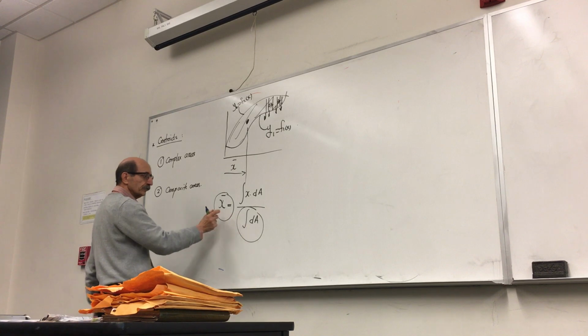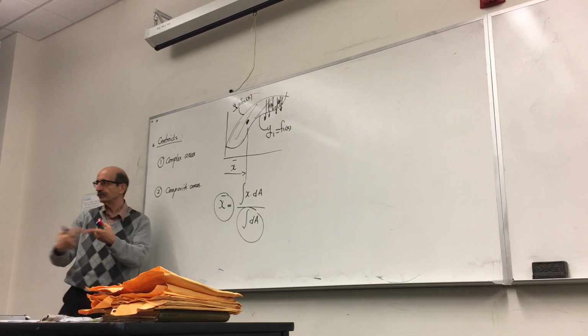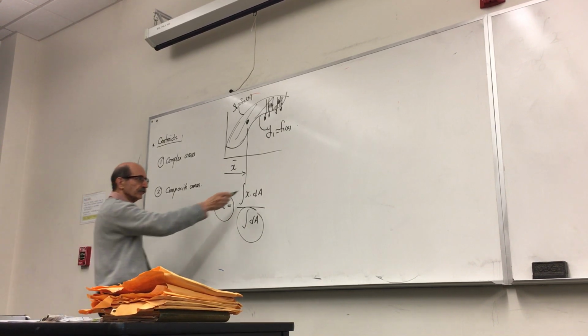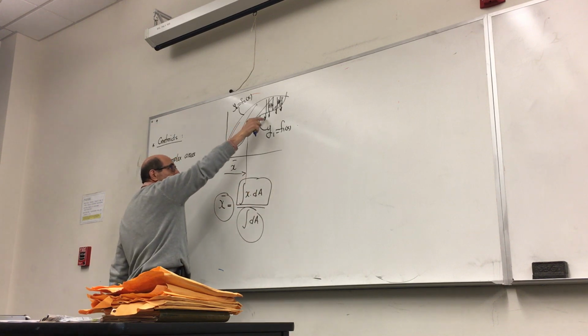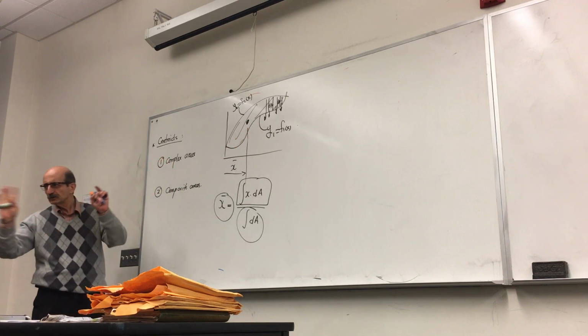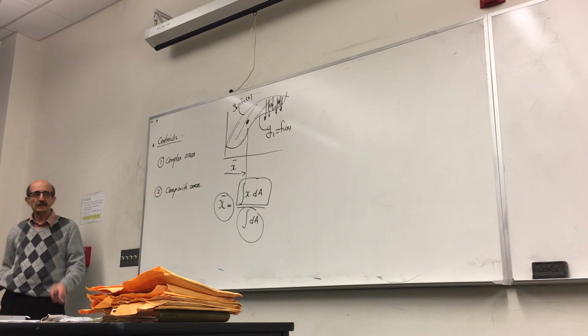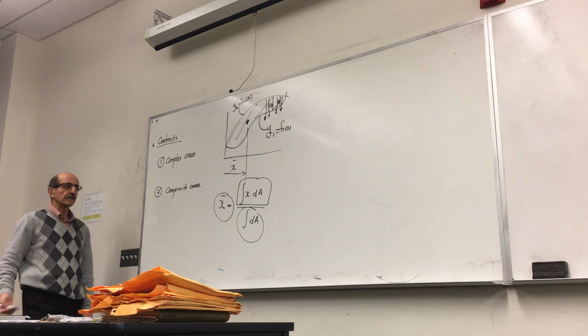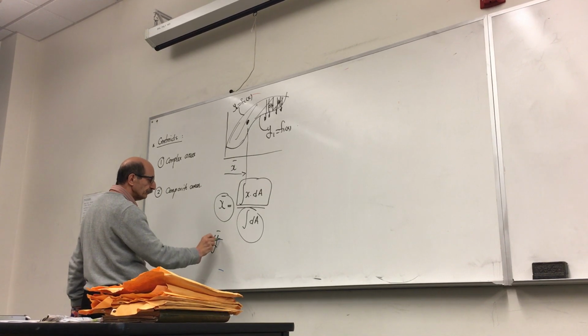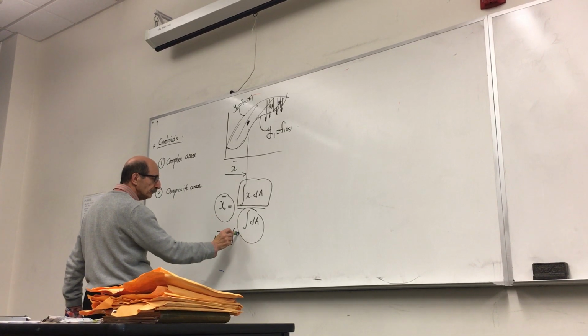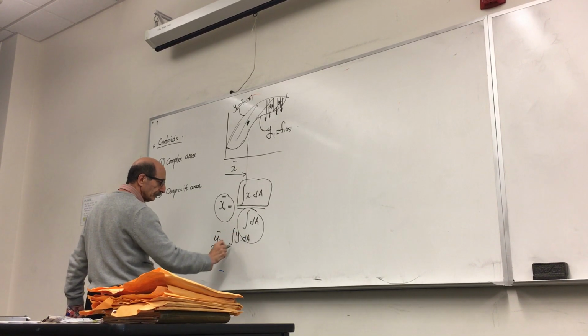If this is a force, this is a distance times force means the moment, right? Is this, is the sum of the product of each of these individual little areas and their moment arm. So you don't have to remember it that way, but at least it's good to know there is this analogy that exists. And the y bar is found from a similar relationship.